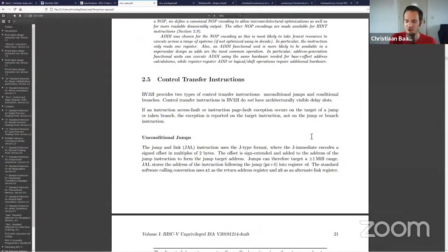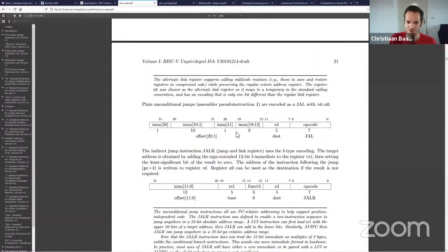Right, so the jump instruction encodes the most significant bit of the address at bit 31, and then suddenly bits 10 down to 1. So this is not just non-contiguous, it's also not ordered from MSB to LSB. This is something our current annotation system does not handle. So it can handle non-contiguous, but it doesn't handle unordered.